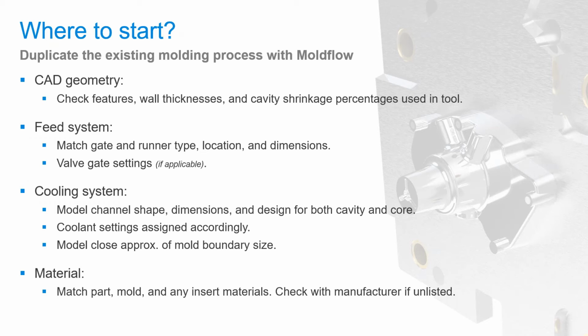The next step is to confirm the material used for Moldflow and make sure it matches exactly what you're using. So within Moldflow, there are preloaded databases that have measured materials in it. So making sure that that measured material matches the material that you're using at your press is key to replicating it within Moldflow. And this also includes mold materials as well as part or mold inserts too.